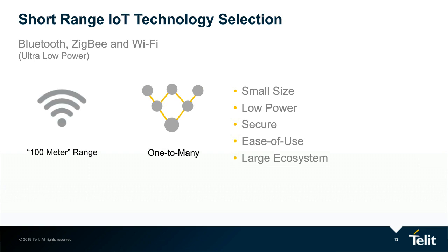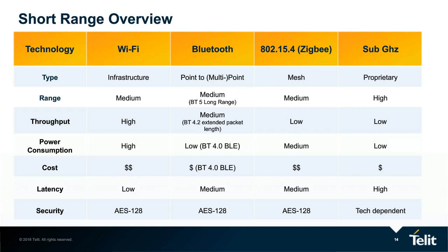So looking at the main technologies from a high level, we currently see this picture. Each technology has of course its own specific use cases and some are overlapping with others. Specifically Bluetooth, starting with the introduction of Bluetooth Low Energy, has given Zigbee a run for its money. Today, I would say Zigbee has no real advantages versus Bluetooth Low Energy, especially since the introduction of Bluetooth 5 and the long-range feature. Instead, Zigbee still has to fight a little bit with the not so good standardization, which often led to implementations adding proprietary extensions, which in return led to not interoperable solutions.